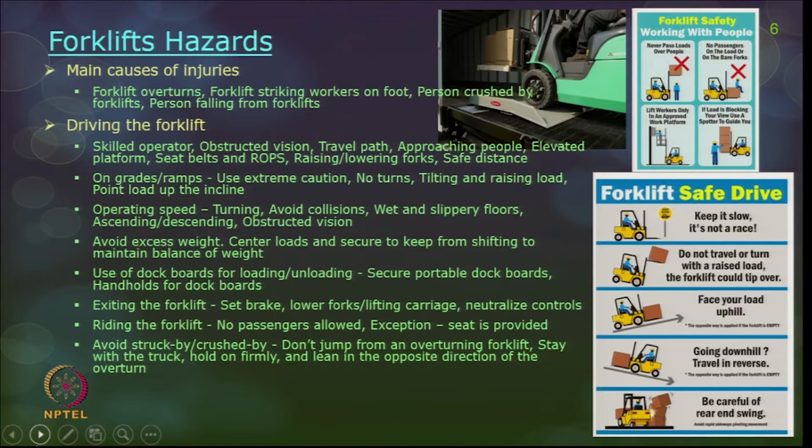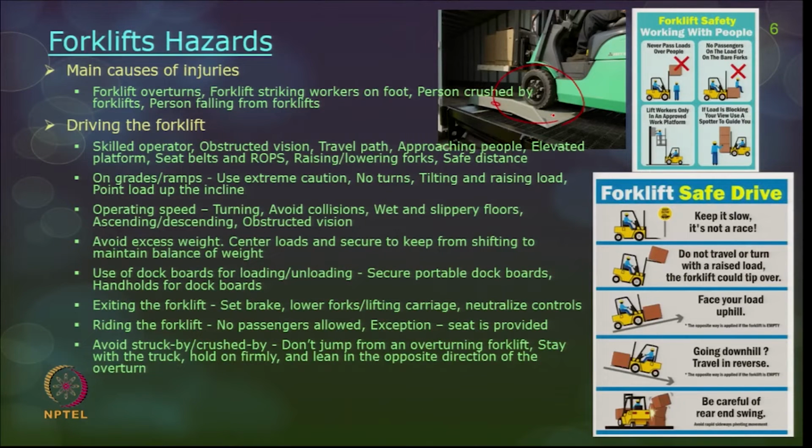Use of dock boards for loading and unloading. So, dock boards are like the stops, as seen in this figure, primarily used for loading and unloading. You should be securing the portable dock boards, and there should also be hand holds for easy handling of these dock boards. When you are exiting or entering the lift, you should be very cautious in putting the forklift in the neutral position, and when you are loading or unloading also, the forklift should be in a proper position.